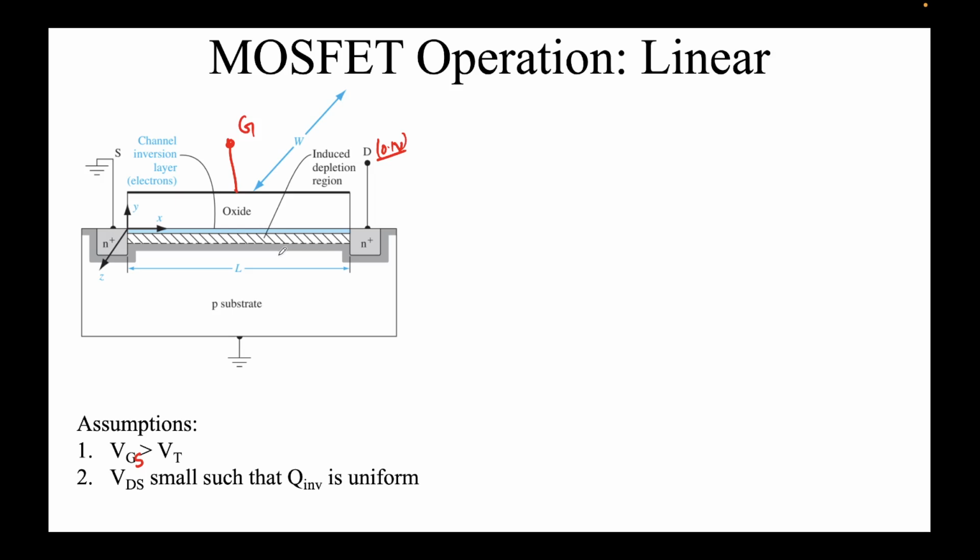Right. So as I said, what is the value of Vg? First it will be phi ms, minus Q ox by C ox. This is the flat band that you need to achieve, minus Q depletion over C ox to cause depletion, which you see in the dashed region, and then finally you have 2 phi f.